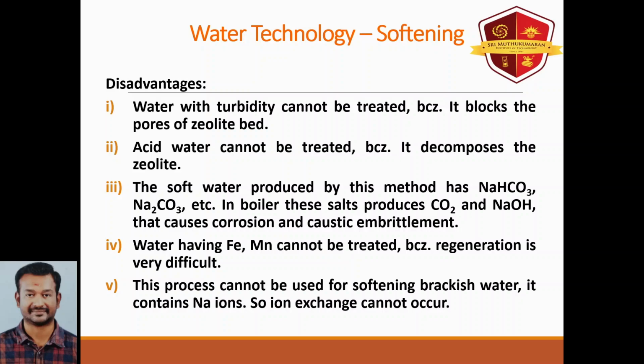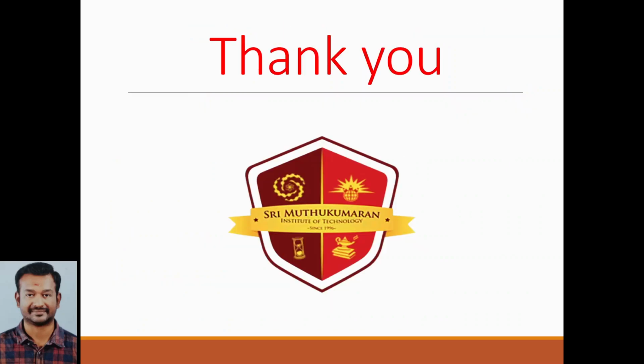The soft water produced by this method contains sodium hydrogen carbonate, sodium carbonate, etc. In the boiler, these salts produce carbon dioxide and sodium hydroxide, which cause corrosion and caustic embrittlement.